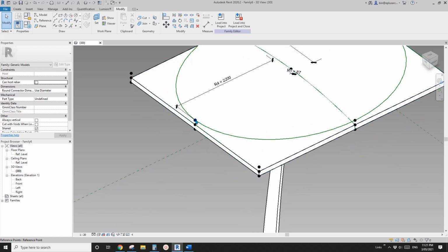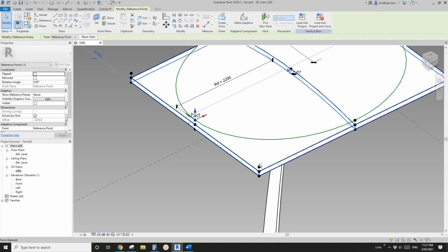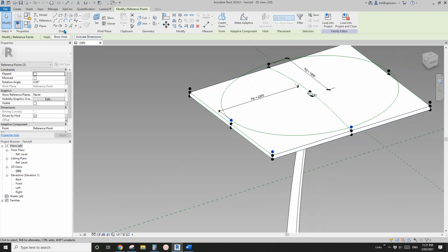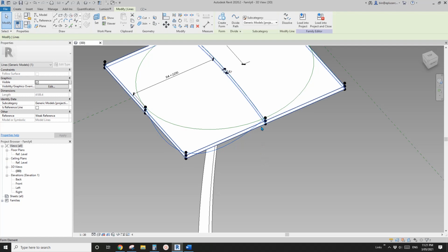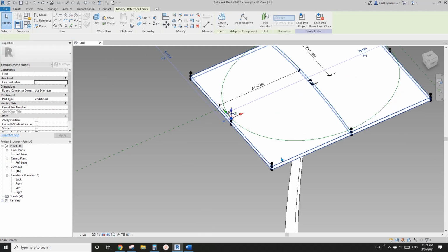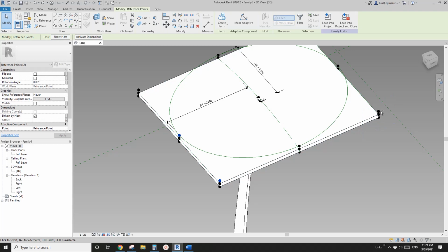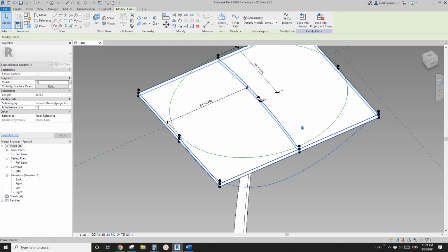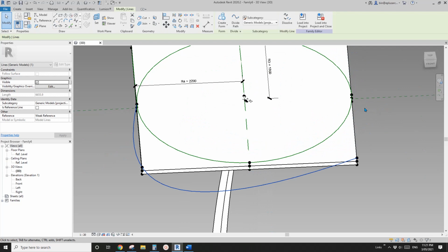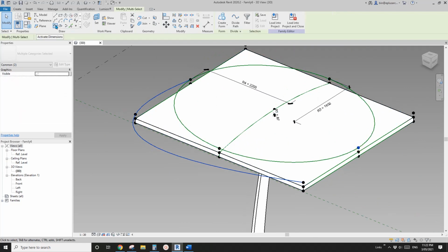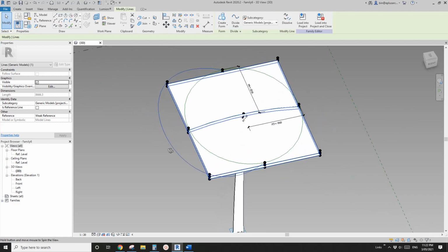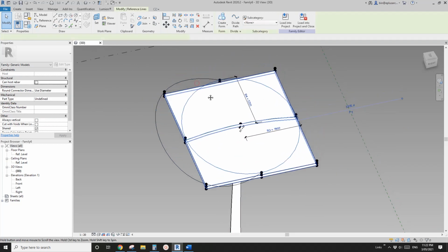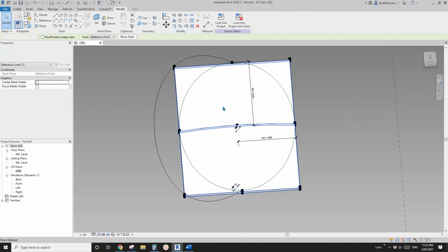So let's do it. So first select this point, and this point, and create a spline. Oh, hang on, not this one, sorry, Control Z. Select this point, and this point, create a spline, and then select this spline together with this point and create another spline. So this will create 1 spline for us.